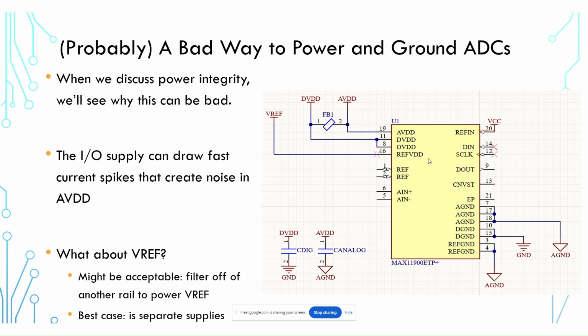And then one other step, add in precision voltage references. That will then provide a stable DC voltage for your reference inputs for your ADC. Everything I've discussed for ADCs also applies to DACs. So just remember that. All this stuff with ADCs, totally acceptable for DACs as well.